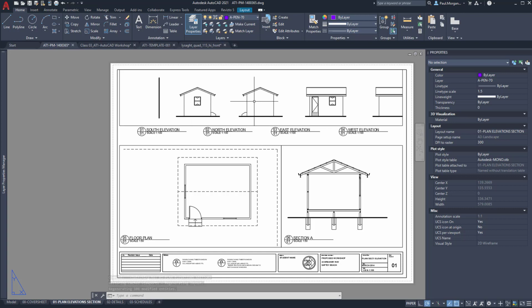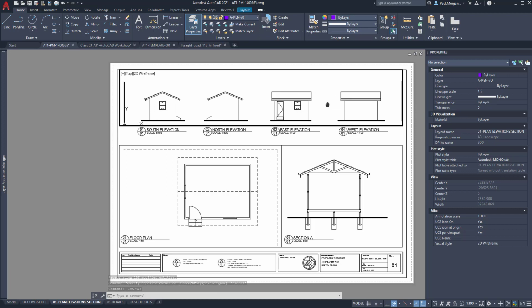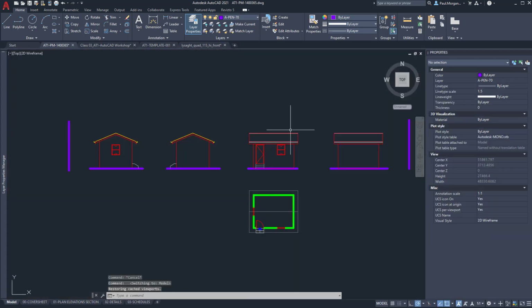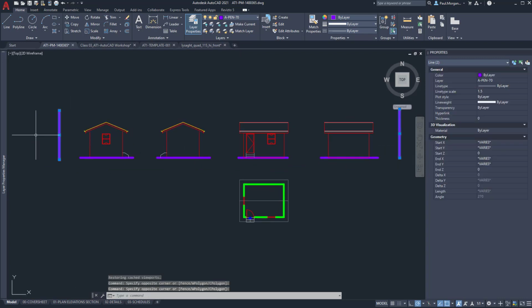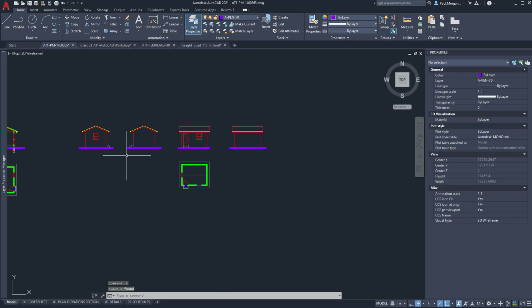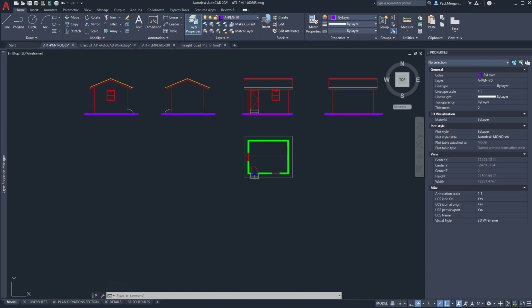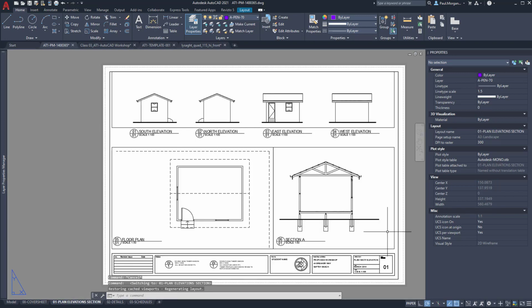So okay, now I can see that my drawings are offset because I moved those drawings across in the model space. So I need to double click into the viewport, drag that across, and I might sit that down. It's somewhere around there. I'm pretty happy with that. Double click and I'm out of my model space. I'll go back to my cover sheet. Whoops, back to my model space, sorry. And I am going to get rid of those two lines for now. So with that done, we're getting the beginnings of what will be our sheet setup.